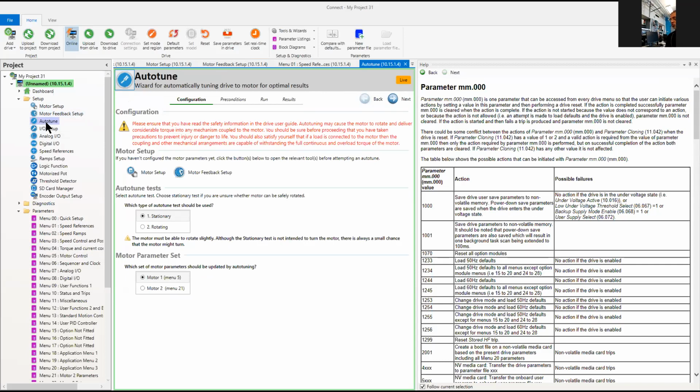For a PID controller, practically you have two options: manually tune it, or go with this one. This program has an option with auto tuning to get some tuning parameters. Please ensure they have nothing attached to it. Okay. Stationary, this one. Next.